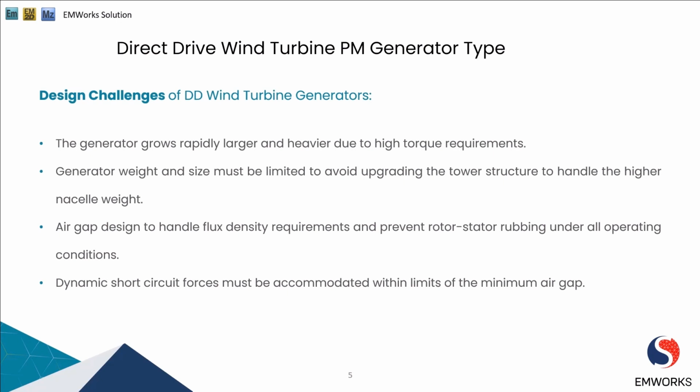Another challenge is an essential aspect of direct drive design involves optimizing air gap to handle the required flux density while preventing rotor stator rubbing under all operating conditions. Achieving an effective air gap design is critical to ensure efficiency and minimal wear and tear. Another key challenge is accommodating dynamic short circuit forces within the constraints of the minimum air gap.